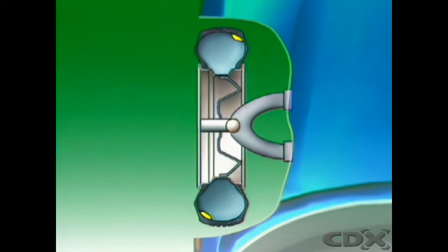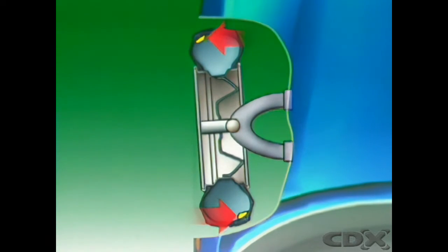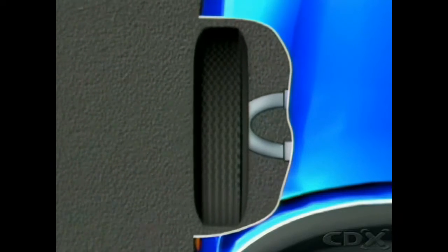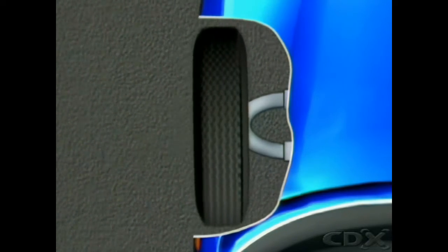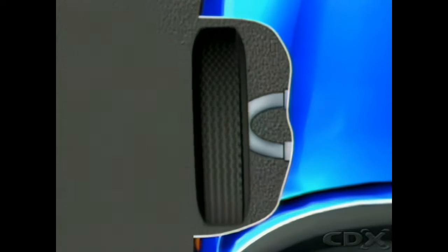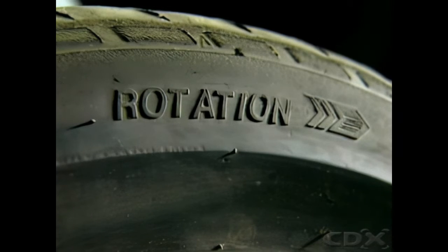Dynamic unbalance causes the wheel assembly to turn inwards and then outwards with each half revolution. As speed rises, rapid side movement of the front wheels causes a sideways vibration or wheel wobble effect at the front of the vehicle. These conditions must be corrected to prevent cupping or dishing of the tread and reduced tread life. Tread life can also be reduced by incorrect wheel alignment.